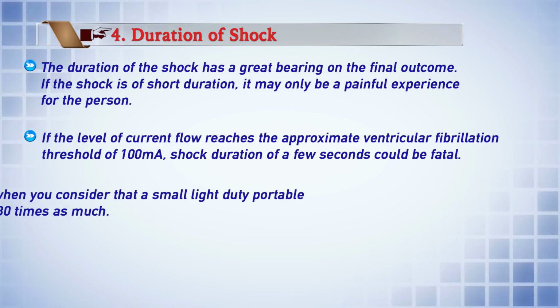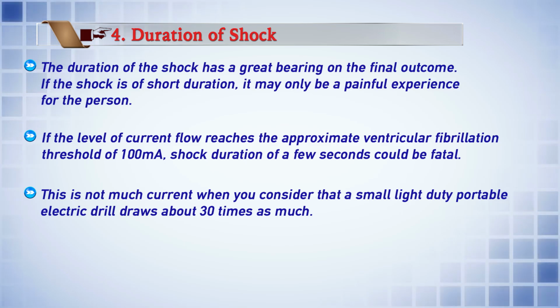This is not much current when you consider that a small light duty portable electric drill draws about 30 times as much. At relatively high current, death is also possible if the shock is of appreciable duration. However, if the shock is of short duration and if the heart has not been damaged, interruption of the current may be followed by the spontaneous resumption of its normal rhythmic contraction.